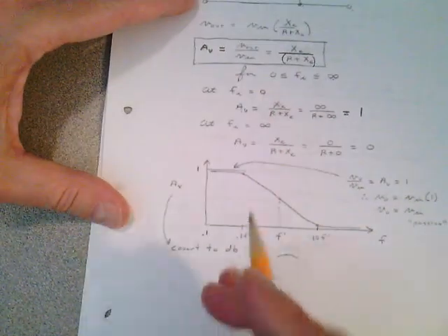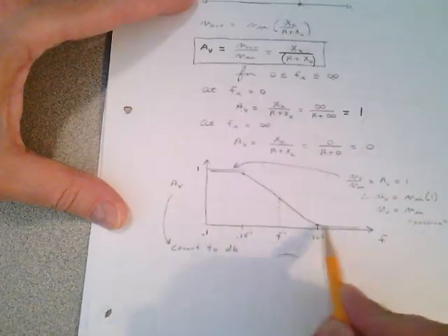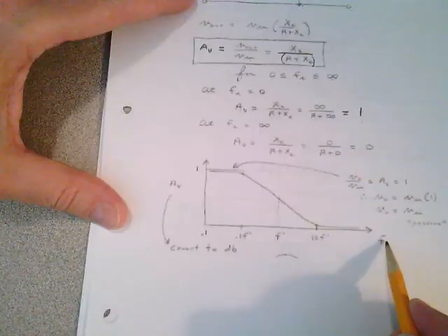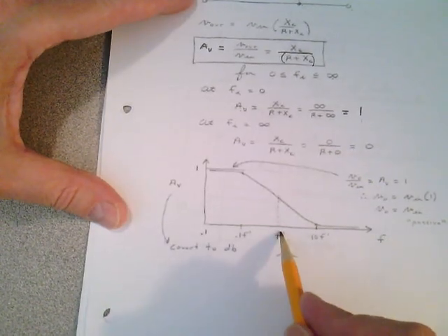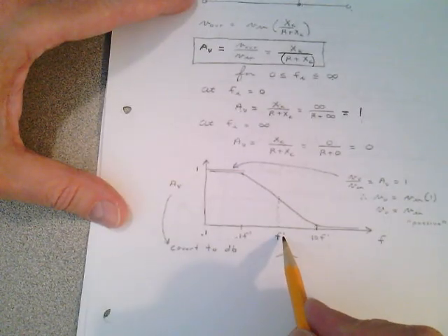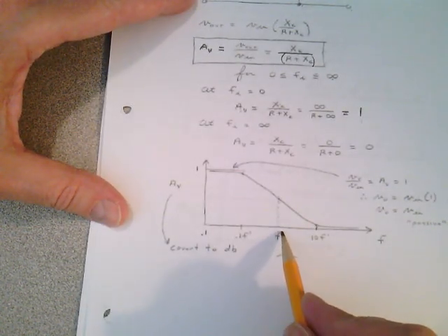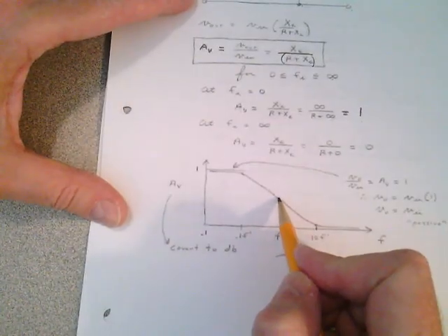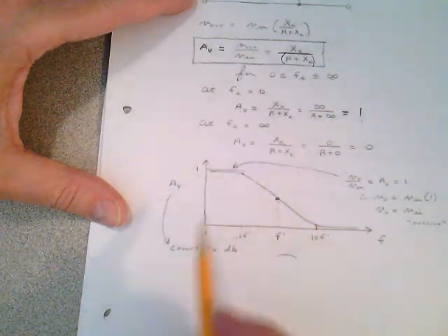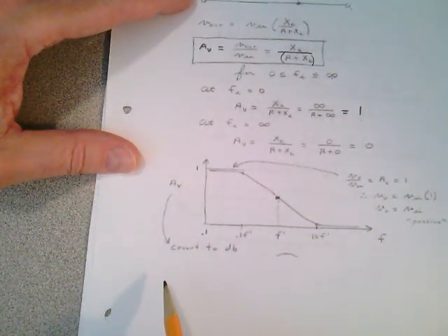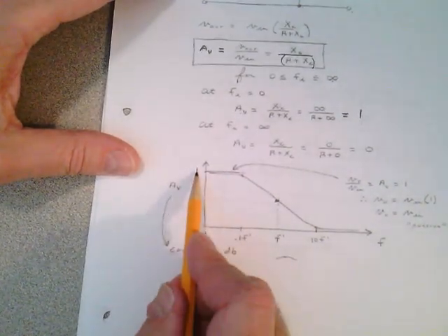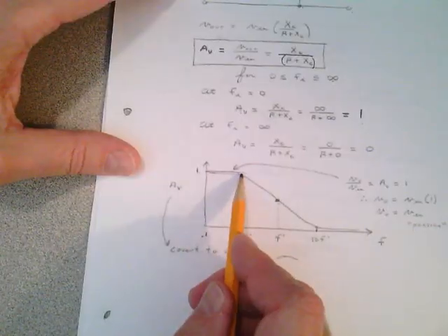So if we do a plot down here of the voltage gain versus the frequency, here's the voltage gain, here's the frequency. Notice that at a particular frequency, I'm going to call just F prime, I'll show you how to calculate that coming up in about 3 weeks. Below that frequency, it basically looks like a direct transfer of voltage. It's 1. This is the ratio here, V out over V in. It's 1, the whole way down to DC.